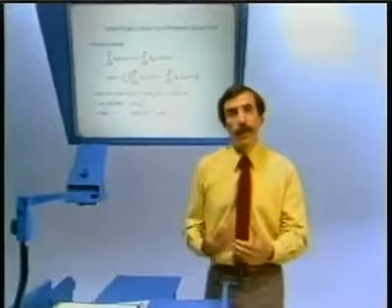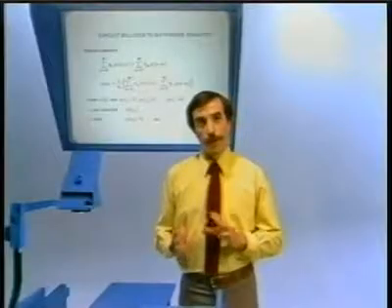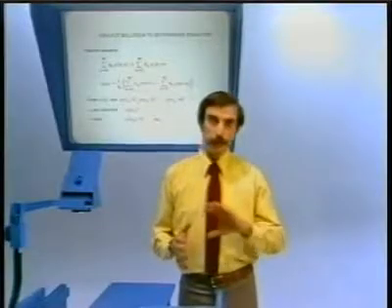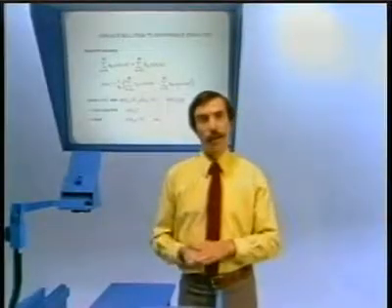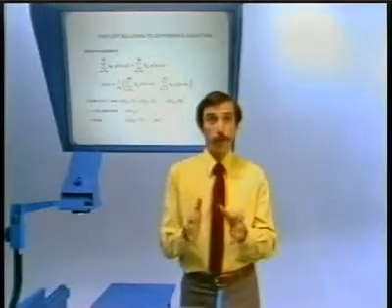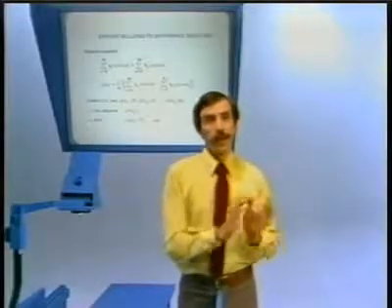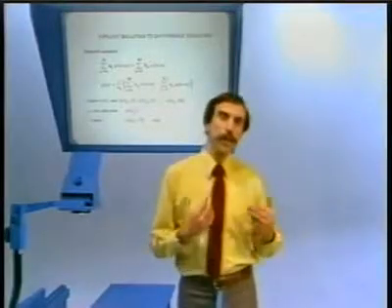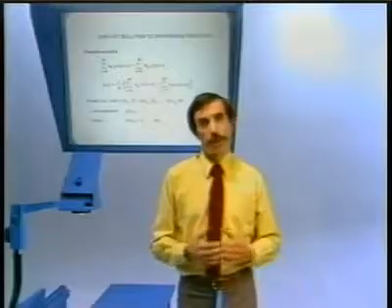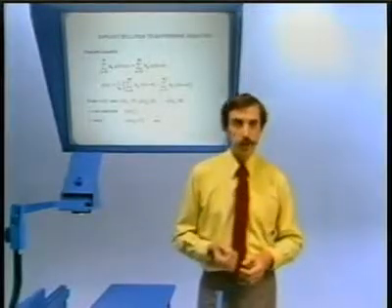Well, how do we get it started? The way we get it started, of course, is through the appropriate set of initial conditions or boundary conditions. And if, for example, we assume initial rest corresponding to a causal linear time invariant system, then if the input is 0 up until some time, the output must be 0 up until that time, and that, in essence, helps us get the equation started.